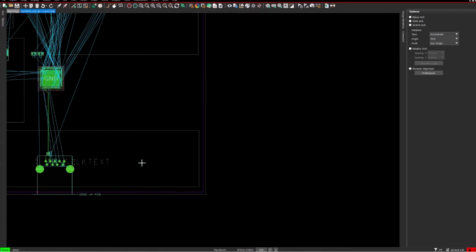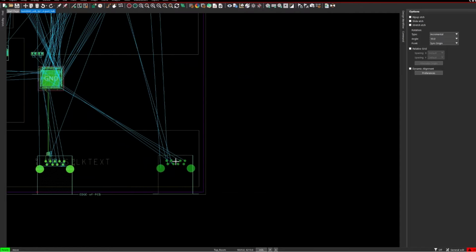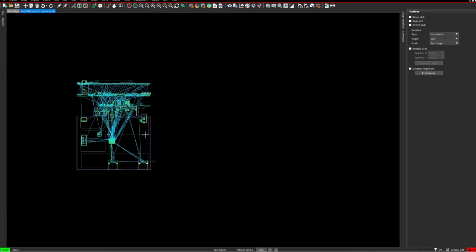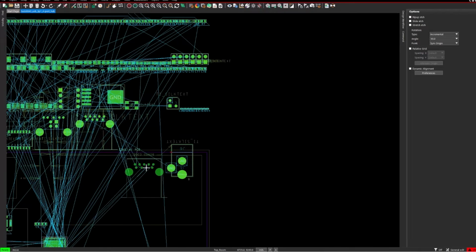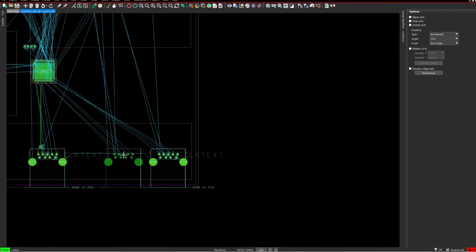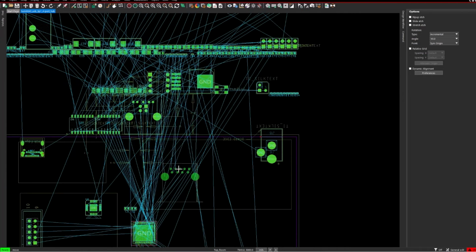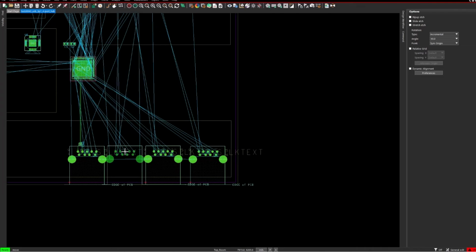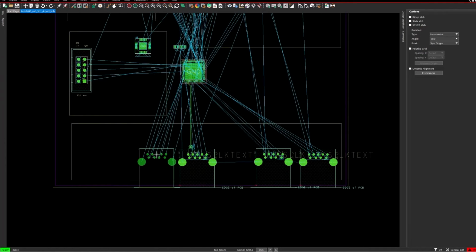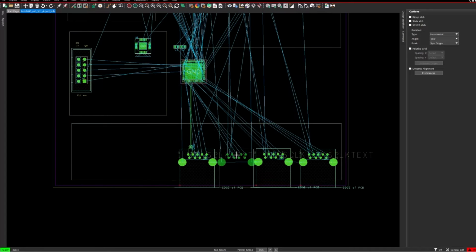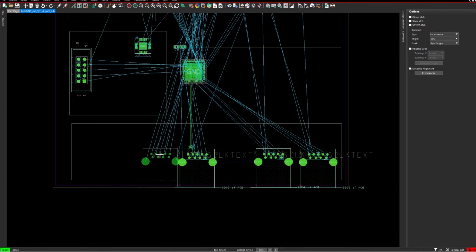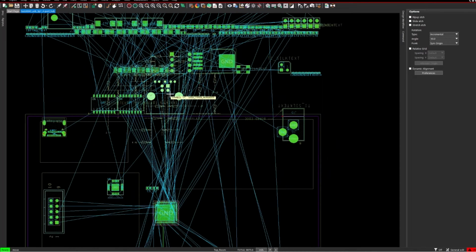Once all that's decided, make sure you place the parts. When you start placing the parts, make sure they're not too far apart. You don't want them too close, but you don't want them so far either, because it would be nice to utilize as much of the space you have as possible. And again, don't place them too close, so that your manufacturer doesn't have trouble assembling the parts on the PCB. Or even if you're assembling the parts yourself, so that you don't have issues physically getting in places because they're too close to each other.